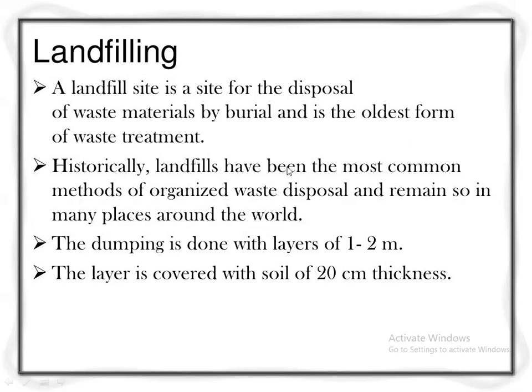In this landfilling technique, the dumping is done at the site in layers of 1 to 2 meters, and that layer is covered with soil of 20 centimeter thickness. This is a layer.